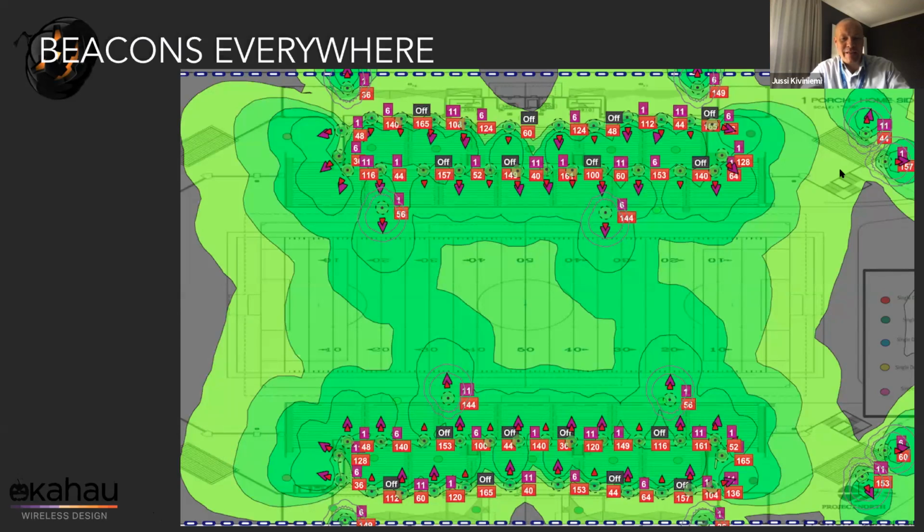And fun fact, you can, for example, model in Ekahau the people sitting on top of your APs. So on the planner, you can drop the APs to like 20 centimeters height, and then you can draw an attenuating area of human fat that lies on top of those APs to attenuate it and all that. So that kind of stuff can be done in Ekahau, but not obviously the curvy slopes and stuff like that.